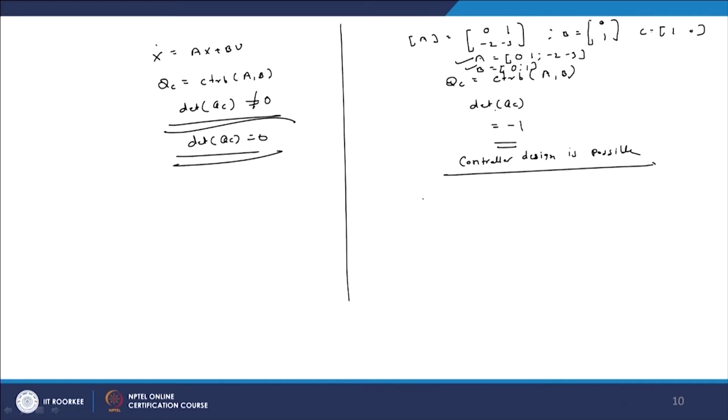Now, about the controller KC, the command is ACKER(A, B, DP). Here DP is the pole placement. Prior to this we have to define DP as [-9 -10].